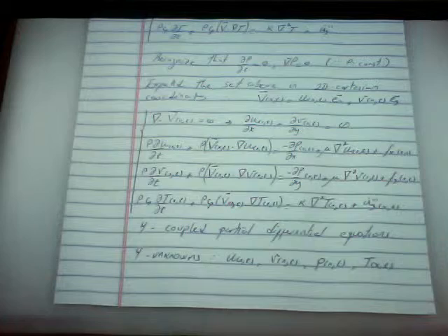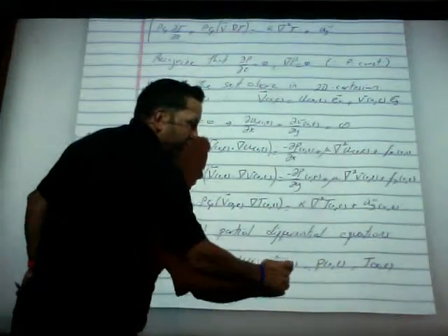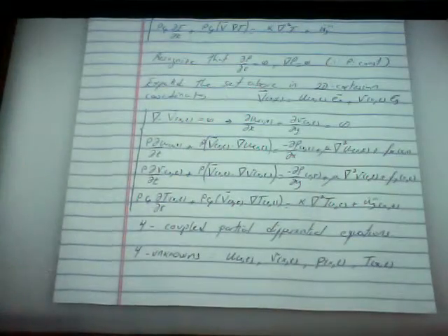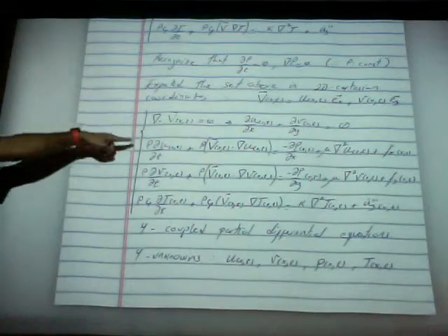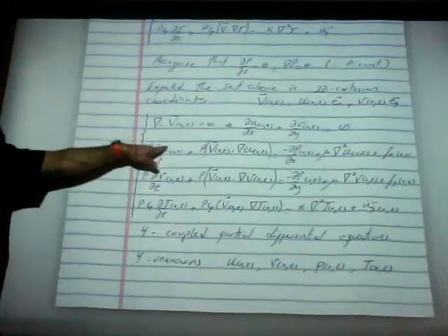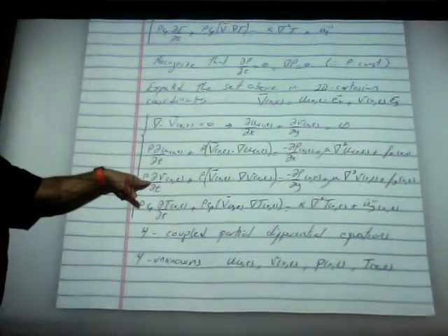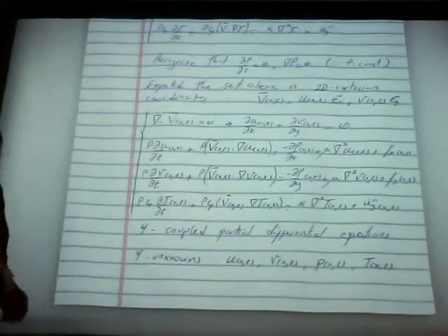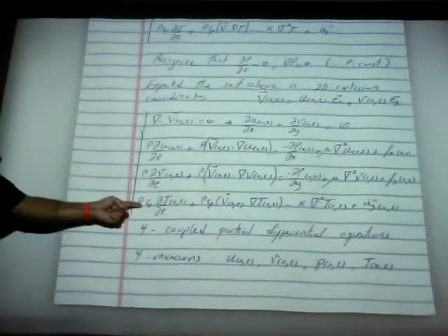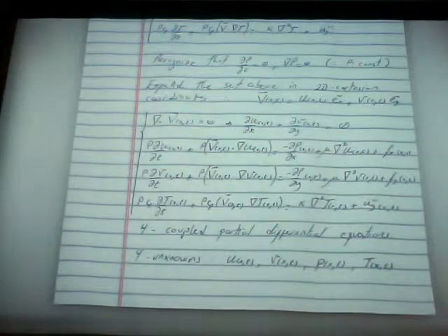Also, the third added complication here is that we have the unknowns u, v, p, and t. And I can see an equation for u, I can see an equation for v, and I can see an equation for t pretty clearly, right? This is an equation for u, it's a transport equation. We expand this one in time and advance. This is an equation for v, okay? We set it up as a transport equation, discretize time, advance, and worry about the right-hand side. This is an equation for t. There's no equation for p. That's a third added complication of this system.